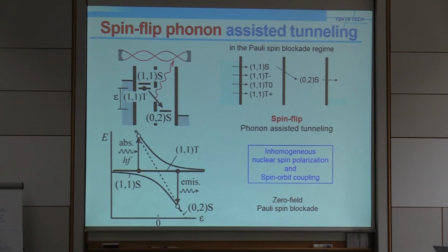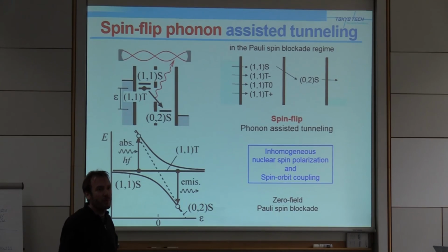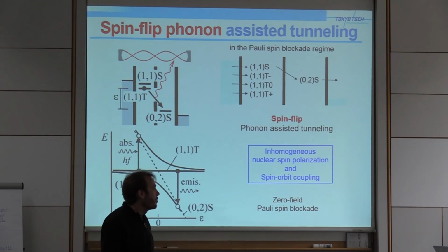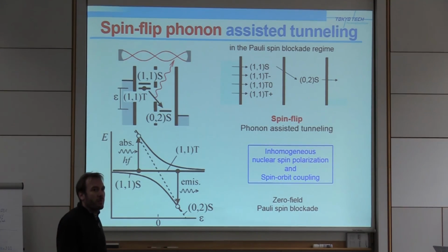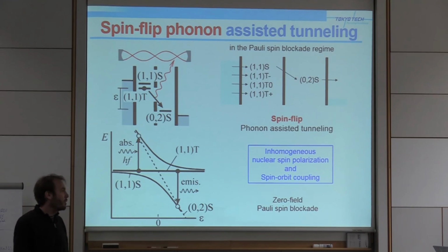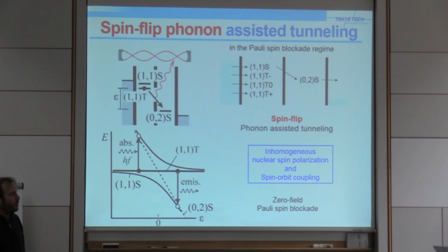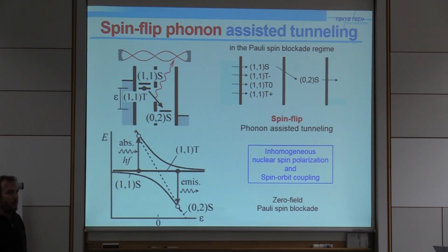Okay, so there are no more questions. I think there's one more question. What would be the most straightforward way in your system to increase this vacuum Rabi splitting? The vacuum Rabi splitting was 7 megahertz or so? Yes. So what would be the most straightforward way to increase it? By design, we need a larger reflection coefficient, actually, by changing some material, or a thicker metal, or increasing the frequency.